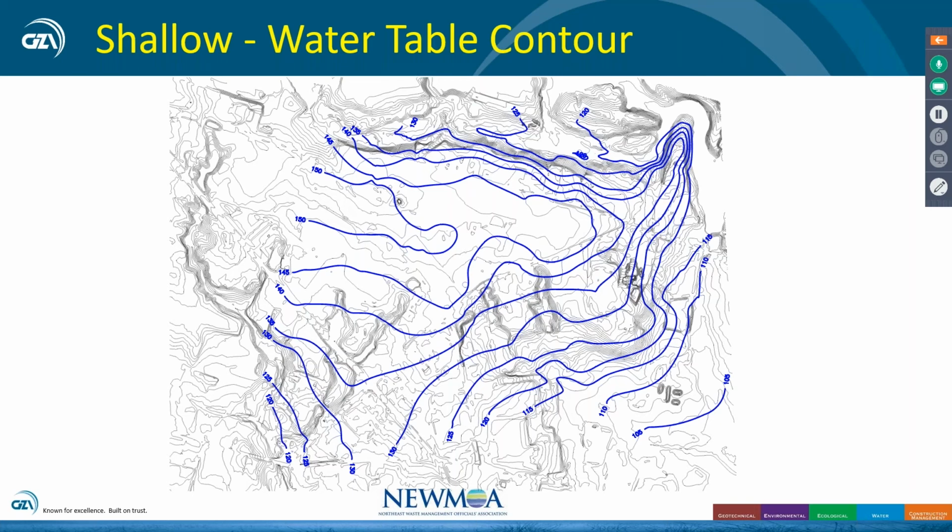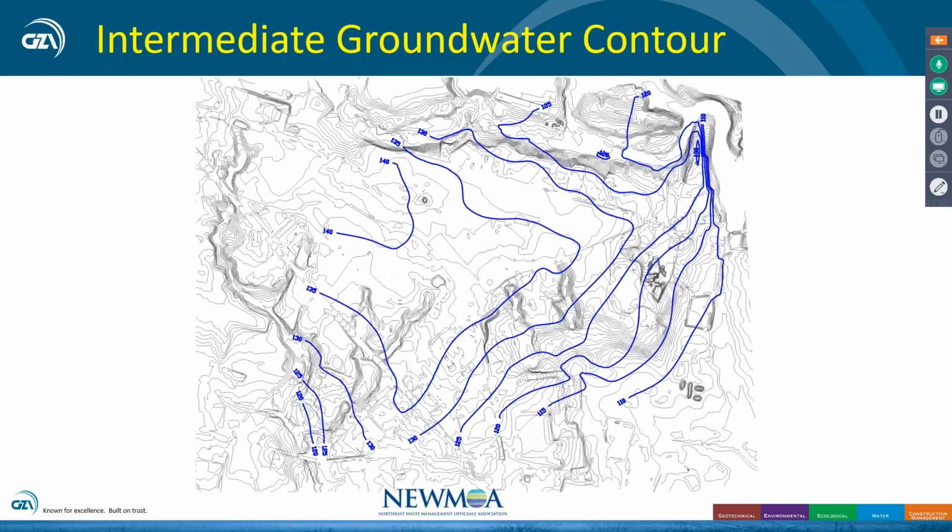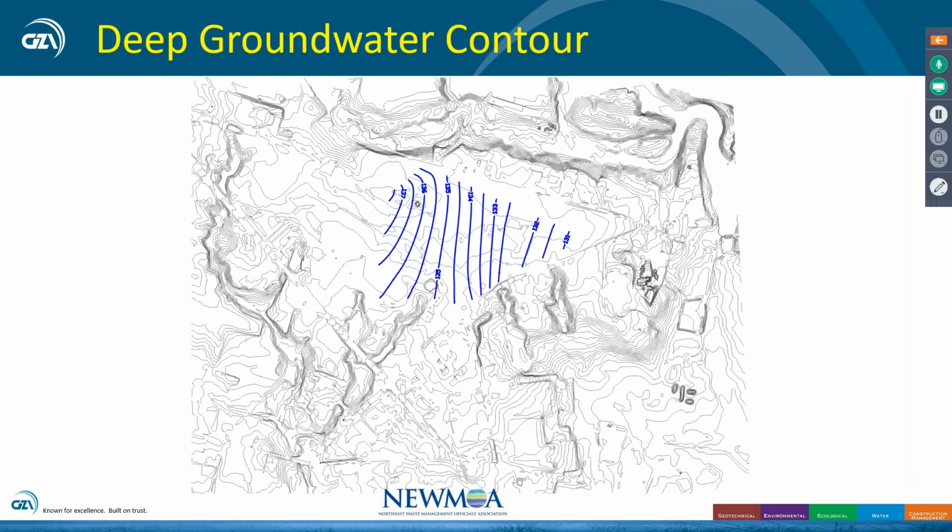One of the things Byron Stone told me, about this little drumlin right here, is we also need to look at ages of things. The drumlin is not a Wisconsin drumlin. This is an Illinoisan glaciation drumlin that was present. And therefore, that really influenced how groundwater flows, as well as some of the geochemistry. A little deeper above a lacustrine deposit, and then further down below the lacustrine deposit, we see an entirely different groundwater flow regime. Fortunately, this is not contaminated also.